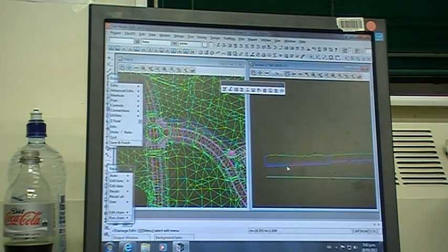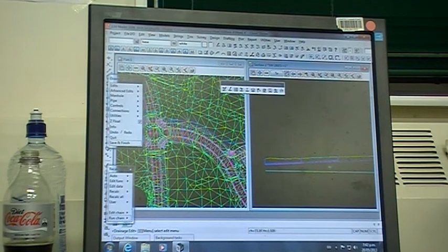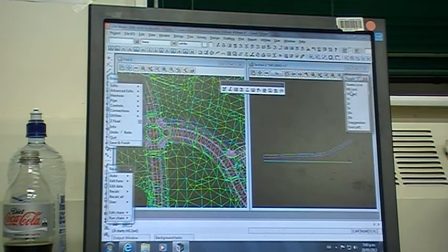It's being built three-dimensionally. If we look at this in perspective, you'll be able to see the pipes and the manholes below the ground. The cyan line running along the bottom is the hydraulic grade line. It's sitting at RL0 at the moment because we haven't asked it to calculate anything. So it's come up with the default grades based on the minimum drop through the manhole that I've given it. 1 to 100, is it the 1 to 100 you do? Yeah, in fact, if I turn on the grades here, just come up to our toggle grades.